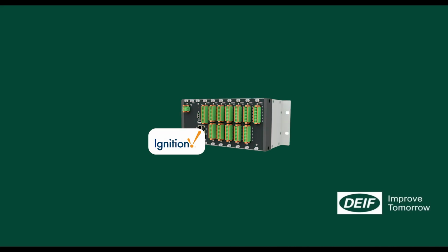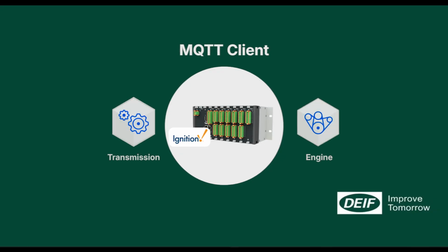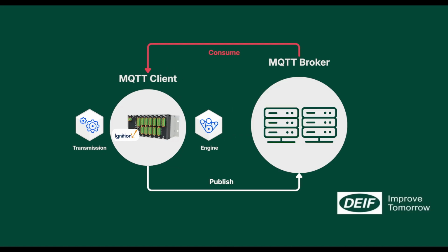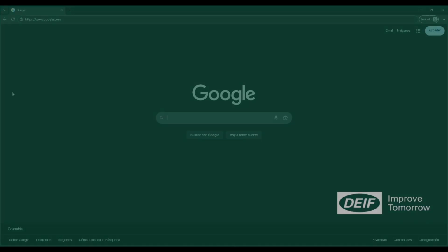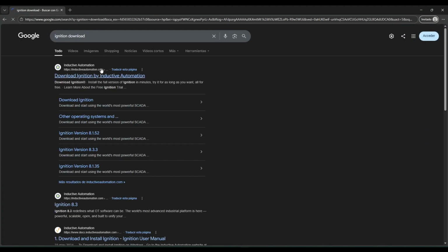An Ignition gateway running in a Podman container on the iE650 PLC can act as an MQTT client by using Cirrus Link's MQTT Transmission and Engine modules. These modules enable the gateway to publish data to an MQTT broker and to consume messages. The MQTT modules can be downloaded from Inductive Automation's Downloads website.